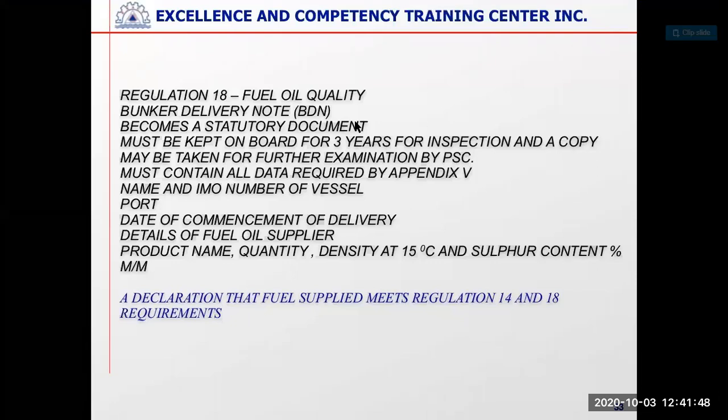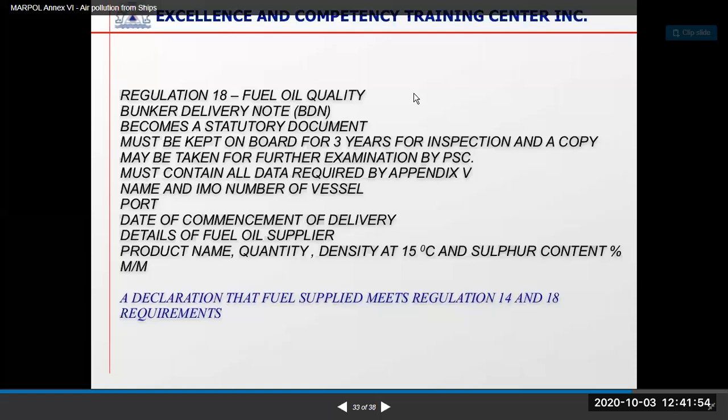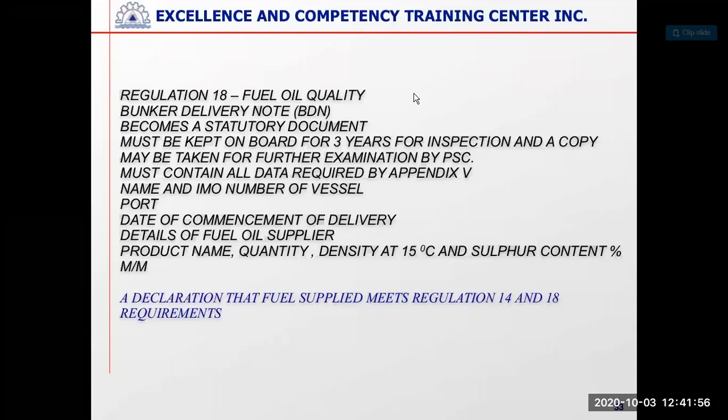Regulation 18 is about fuel oil quality, which is controlled by the bunker delivery note from the supplier. Then you should have samples, and you have to retain the bunker delivery note and the samples for 3 years. There are special requirements for bunker samples, the size of bottle and everything.